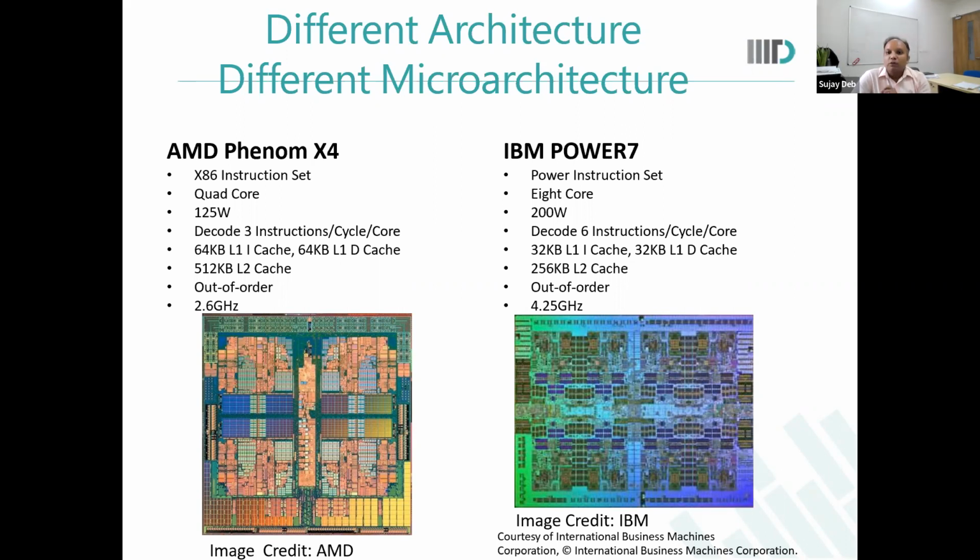Depending on whether your processor by default takes one operand from accumulator and stores the result in accumulator, your assembly code or your program will vary. This is called machine model, and it is part of the ISA. The machine model is nothing but where your operands are coming from and where your result is going.